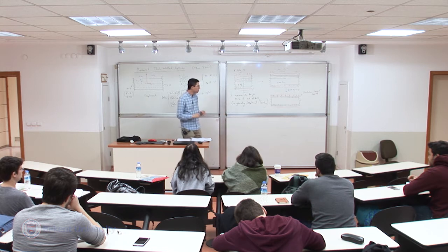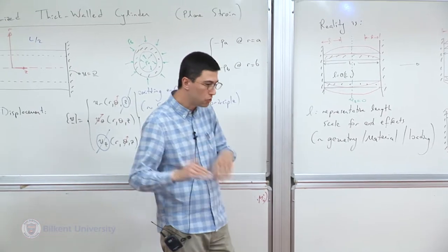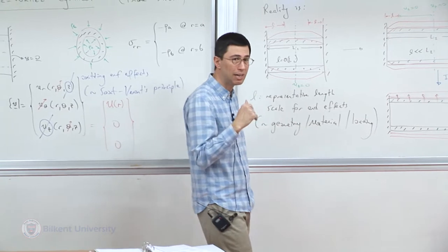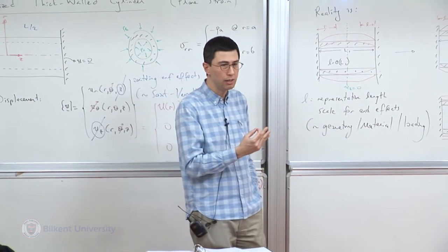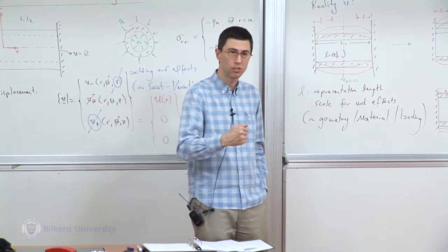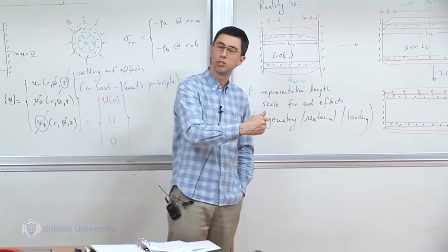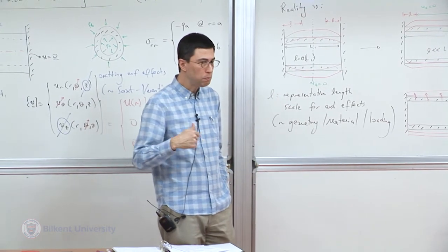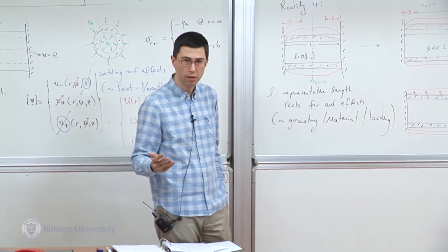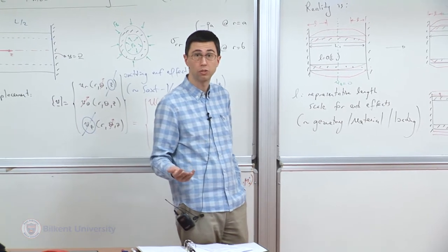For instance, there are problems where the stress variations are extremely rapid, like at the tip of a crack. If you want to resolve that variation very accurately, versus you try to do an analytical solution and enrich your numerical solution with the analytical solution at a crack tip, you can speed up your computation 100 to 1,000 times. That's almost 2 to 3 orders of magnitude.